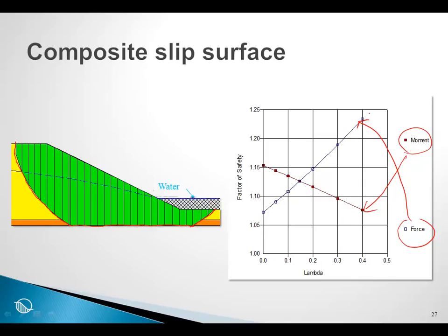Now there's another very interesting observation about this plot, is that the Spencer, for example, is lower than the Bishop. And what this demonstrates is that simple does not mean erring on the safe side. We still hear people say sometimes, I will just do a simple analysis and err on the safe side.